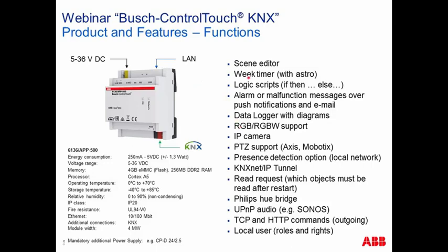Here's a summary of the main functions. A scene editor is integrated, so light scenes can be created. A powerful timer is integrated with Astro function. Very powerful and unique is the logic script, so you can create logical functions with it. Ilya will show you how it works in principle. Alarming and malfunction messages can be sent. Data, analog values for example, can be logged and shown in any graphical diagram.